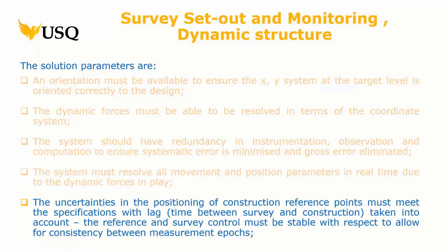Okay, and with the positioning of the construction reference points, there's going to be a lag time. So you say to someone, that's where you're going to put the center of the column formwork, right? And the guy says, okay, I'll do that. And you say, no, hang on, we're moving it because the building's moved, right? But if you go through it mathematically and do it correctly, it doesn't matter if the building moves. But you should minimize the lag time between the survey and the construction, because other things come in, which means the surveying is going to happen while the construction is happening. That's what it really gets down to, which is not easy.